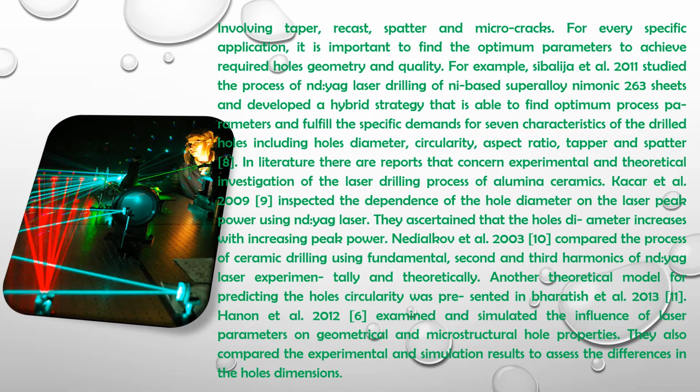2011 studied the process of Nd-YAG laser drilling of Ni-based superalloy and developed a hybrid strategy that is able to find optimum parameters and fulfill the specific demands for seven characteristics of the drilled holes including hole diameter, circularity, aspect ratio, taper and spatter.